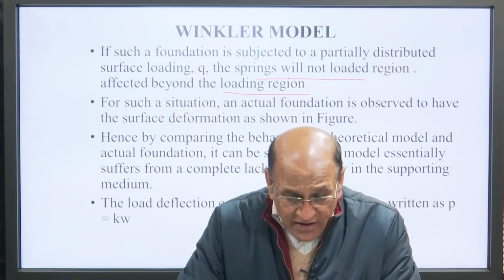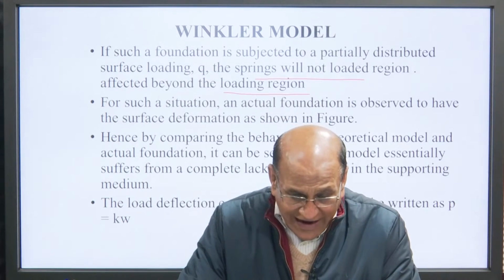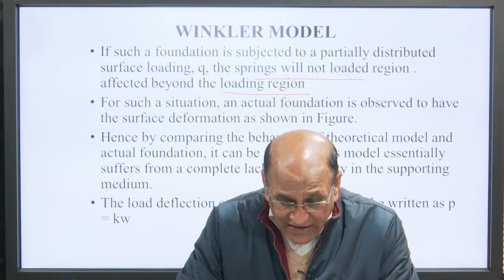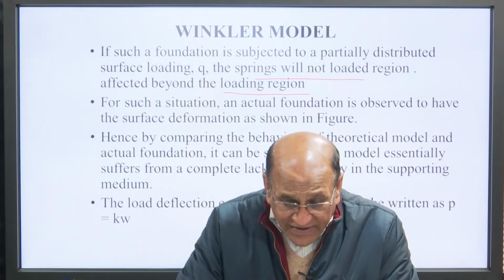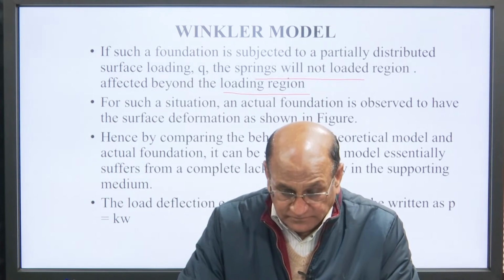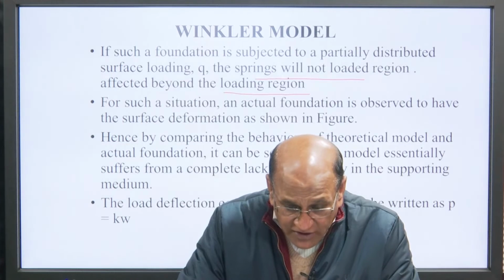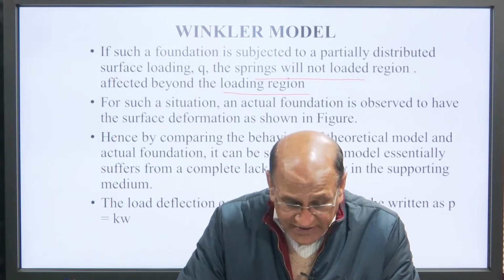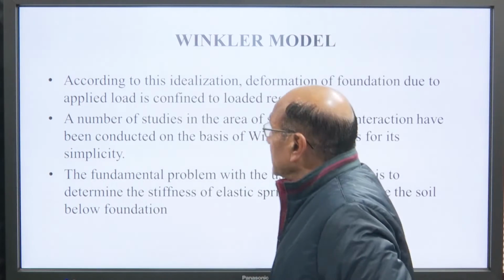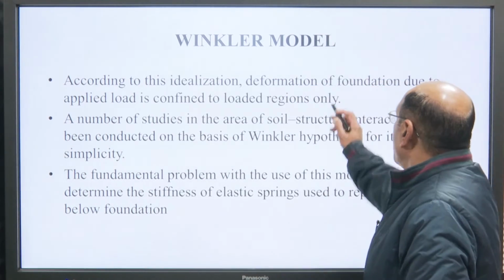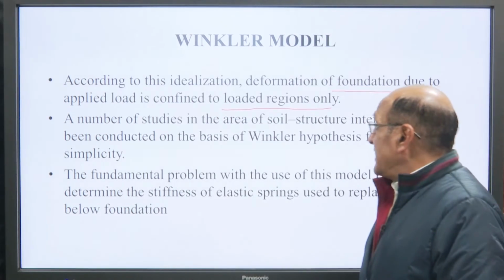Hence, by comparing the behavior of the theoretical model and the actual foundation, it can be seen that this model essentially suffers from a complete lack of continuity in the supporting media. The load deflection equation for this can be written as P or Q is equal to KW, as we have discussed earlier. According to this idealization, the deformation of the foundation due to the applied load is confined to the loaded area region only.